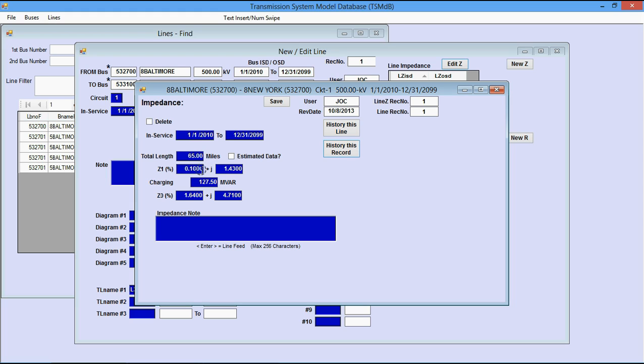But you got length, impedance, zero sequence impedance, and at some point I would add the ability to say what conductors are involved in this line and do a validation between the conductors in the distance and the impedance. Try to guarantee that you don't put an impedance in that doesn't seem to match distance and conductor.